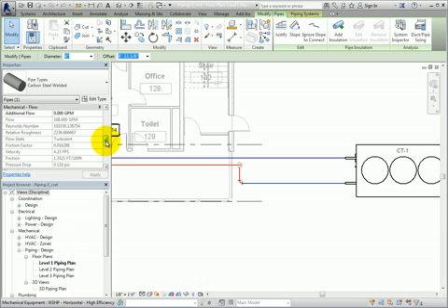There are several charts, tables, and sliders that are used to size pipe. I'll use a standard pipe sizing chart. In this example, I'll use a head loss or friction method at 2.5 feet of water per 100 feet for imperial units, and 245 pascals per meter for metric units. I'll also make sure the fluid velocity in the pipe does not exceed 4 feet per second for imperial units and 1.2 meters per second for metric units.